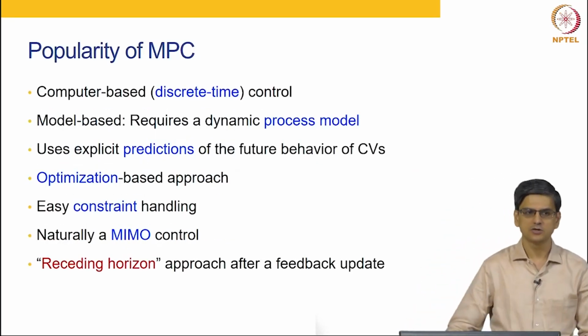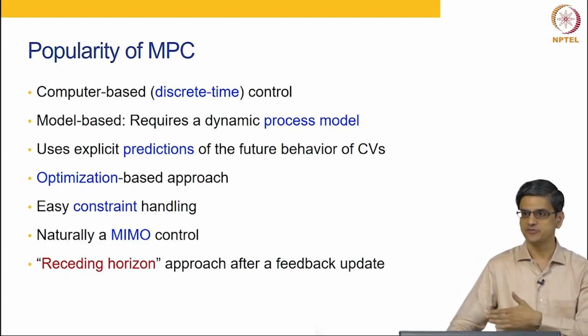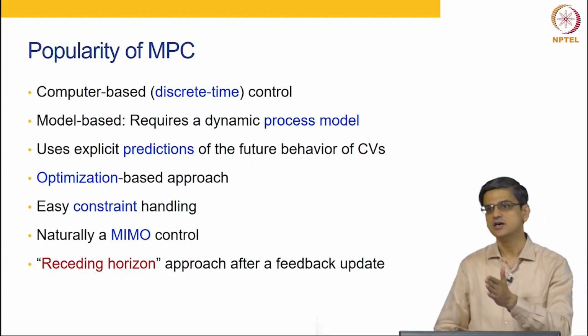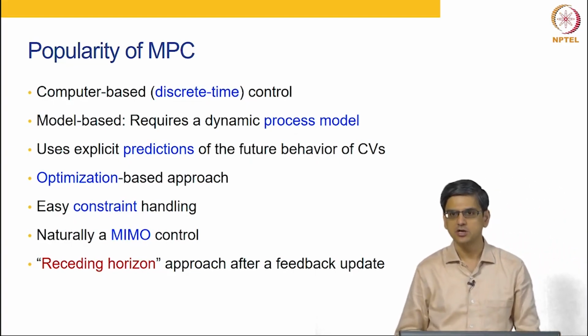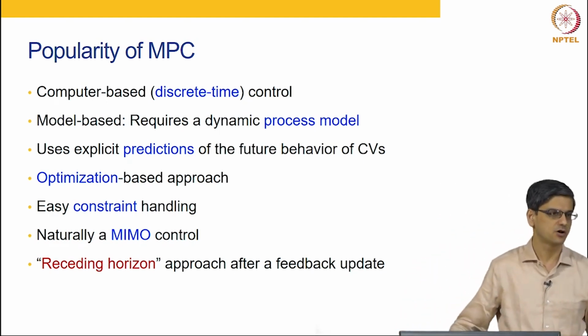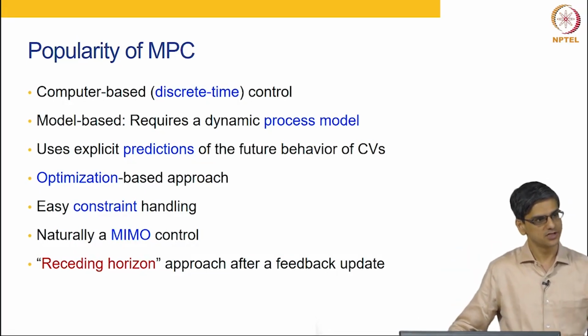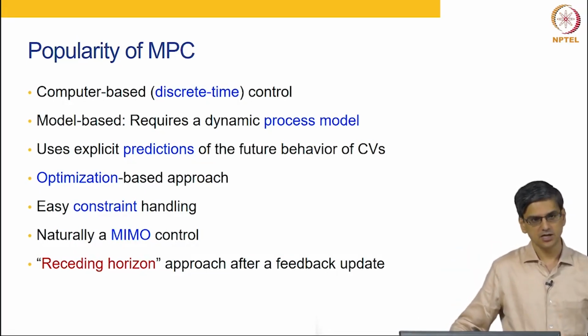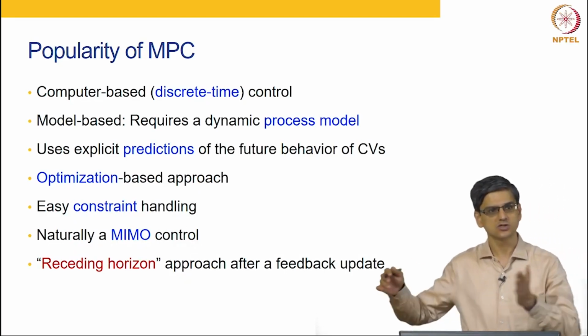So what we talked about, the popularity of MPC, is because it is a computer based approach, and as I mentioned, model predictive control. So it's model based. We use models to predict the behavior in the future, and then we use some kind of an optimization to figure out the best manipulated input moves in the future, implement the current input move at this time, and repeat the entire process all over again.